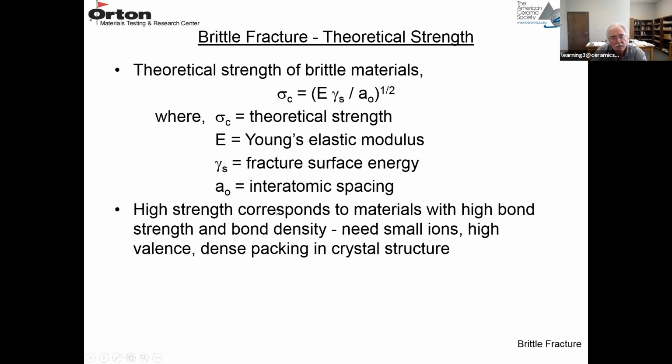So if you have a high strength material, again, just like for elastic modulus, you need high bond strength and high bond density. You need small ions, high charge, or high valence, and dense packing in a crystal structure. So when you have a high strength material, you're also going to have a material with a high elastic modulus.